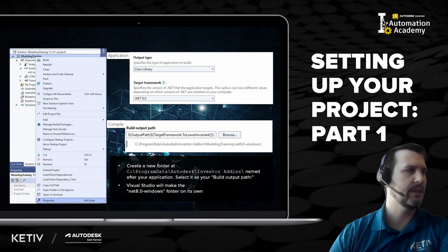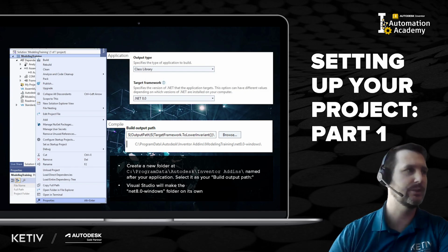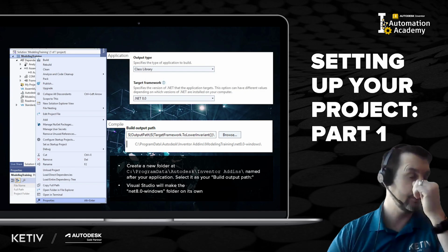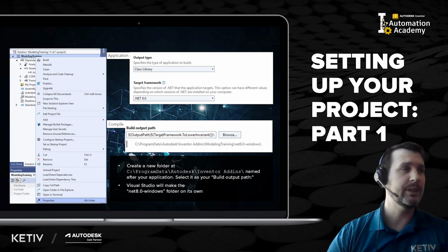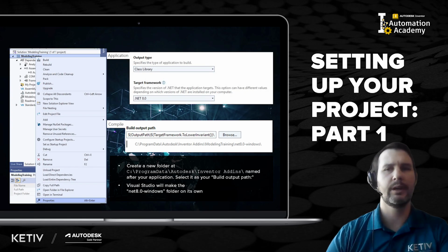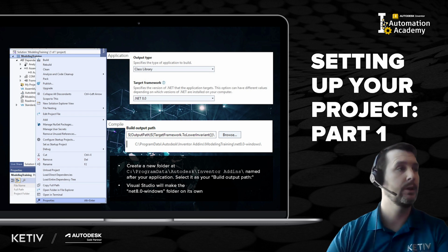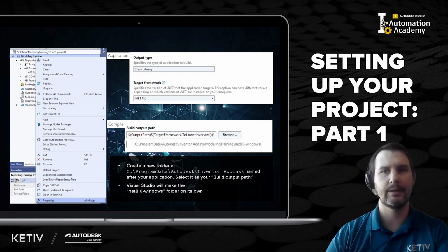And that's going to give us these options. Actually, a whole host of options that we'll slowly scroll through and do some changes on. So first off, it should be this way, but just verify that the output type is a class library. We want to, because we're looking at Inventor 2026, or 2025 is also this way. Anything before that will be different. But for those 2 years, our target framework is going to be .NET 8.